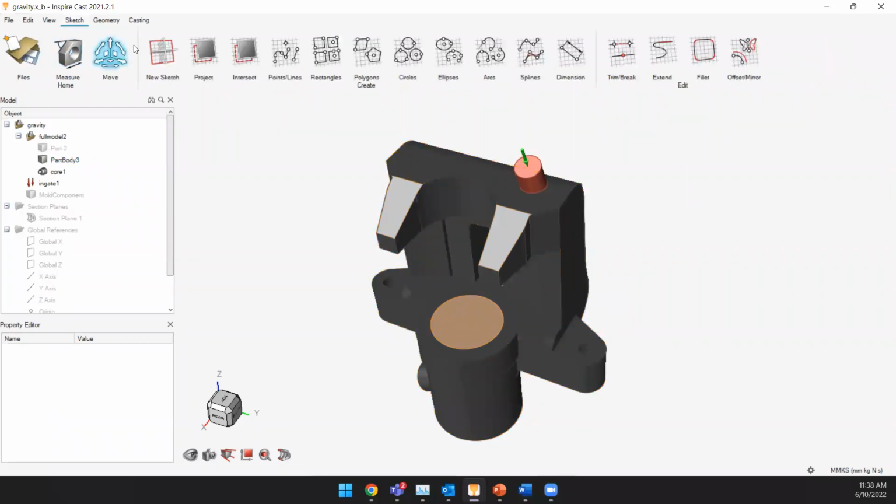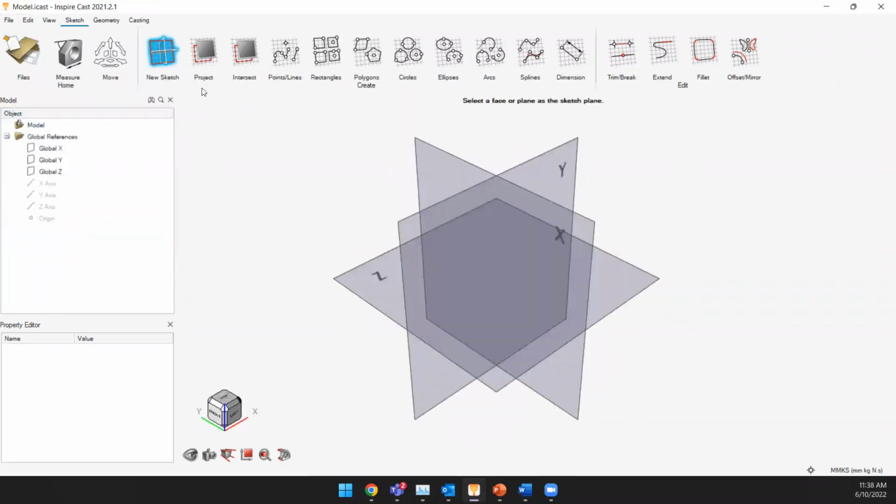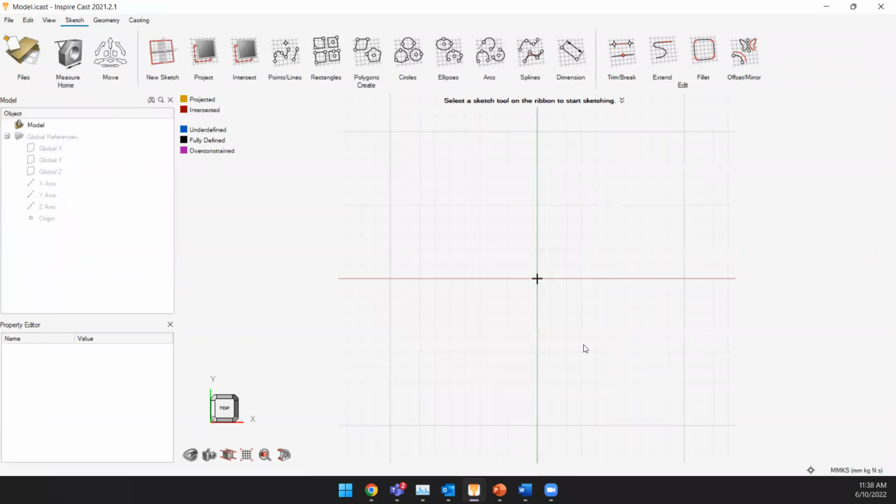You can just start sketching your geometry right over here, and then go ahead and do your analysis. Let's say you start a new sketch. It's as simple as any other tool. Like I said, the snap filter is something where, if I'm trying to draw, it just snaps onto the grid over here. And you can edit the grid in the preferences as well. Let's say this current grid is 9 millimeters. You can edit the size of the grid. So you can do all kinds of stuff right in here in the software.